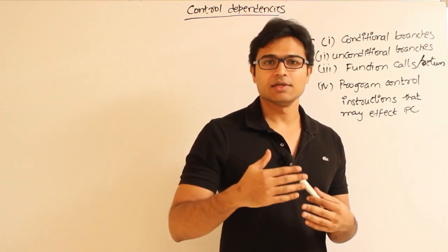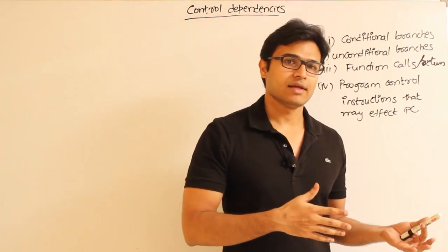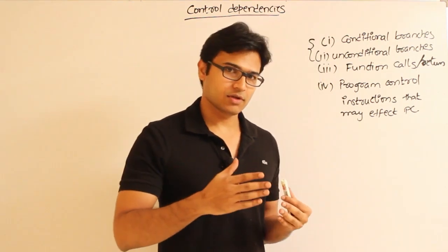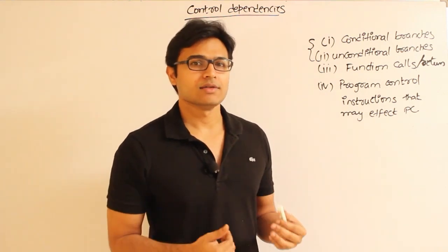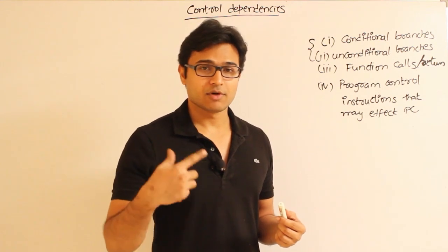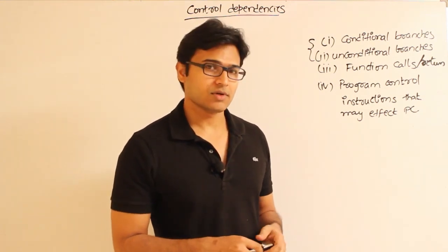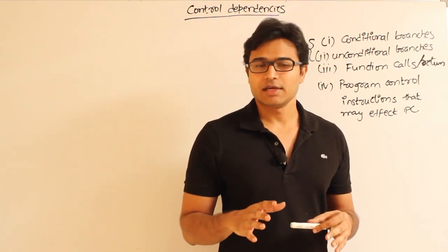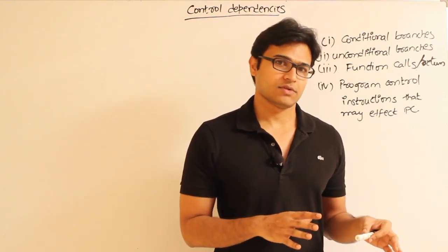So we skip the instruction based on some flag, skip if 0 flag, skip if carry flag, like that. Based on some condition, we are skipping the instruction. They also affect the program counter, right? Because we increment the program counter. So anything that affects the program counter can be considered a branch type of instruction.